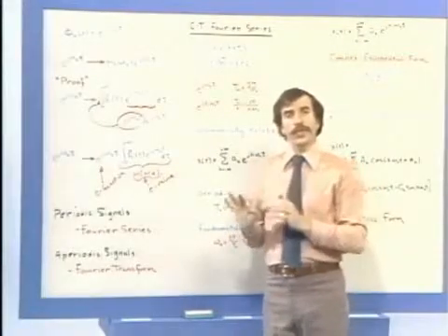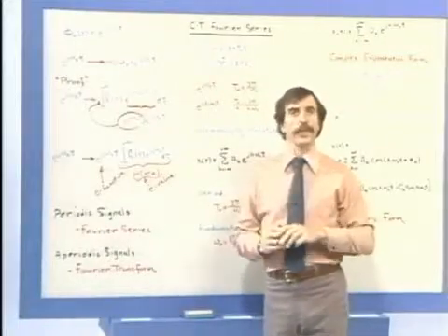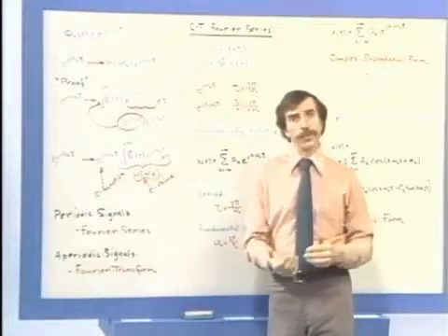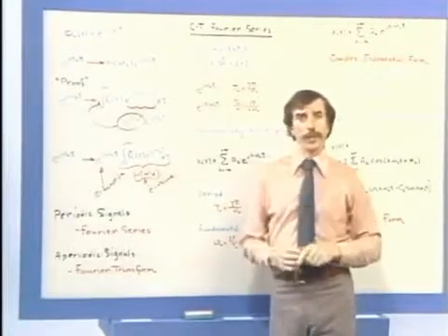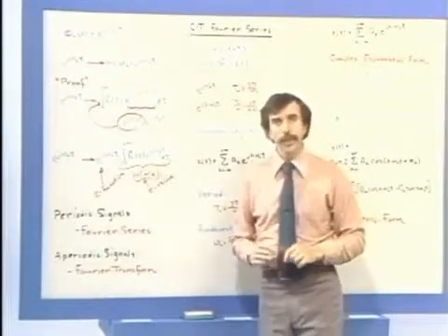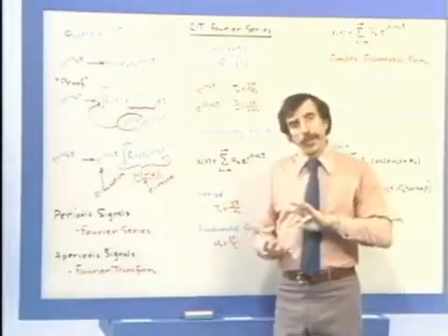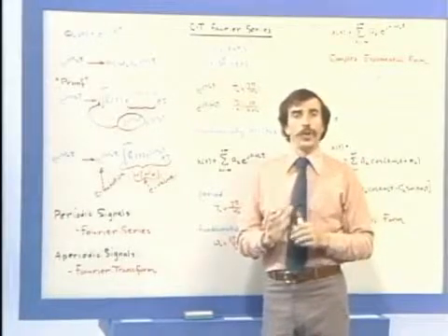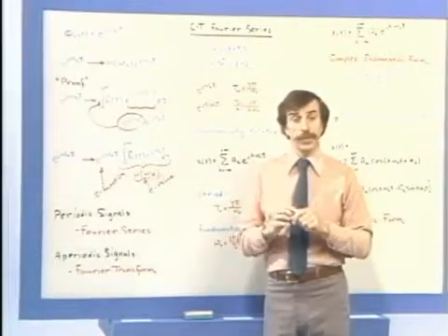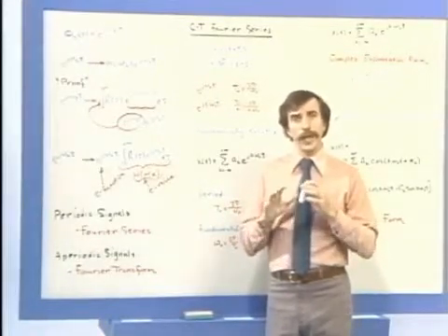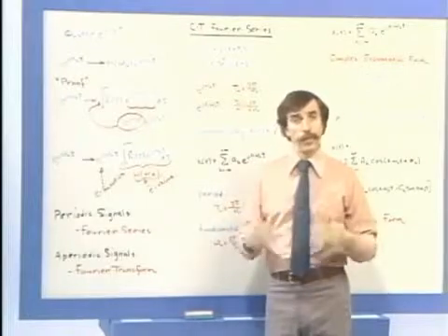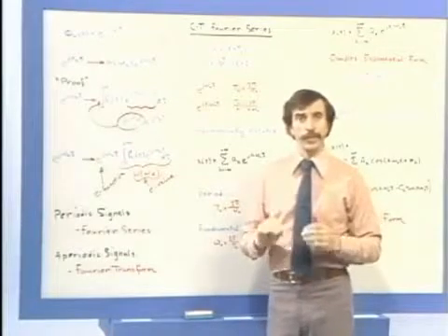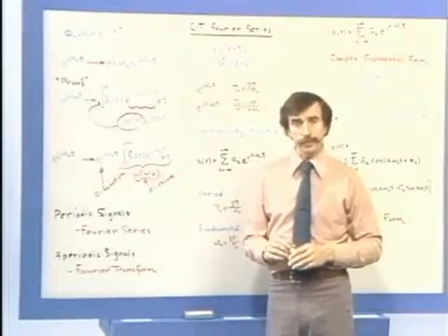Okay, now it's because of the eigenfunction property that complex exponentials are particularly convenient as building blocks. Namely, you put them through the system, they come out with the same form and simply scaled. The other part to the question related to the strategy that we've been pursuing is to hope that these signals can be used as building blocks to represent a very broad class of signals through a linear combination. And in fact, that turns out to be the case with complex exponentials.